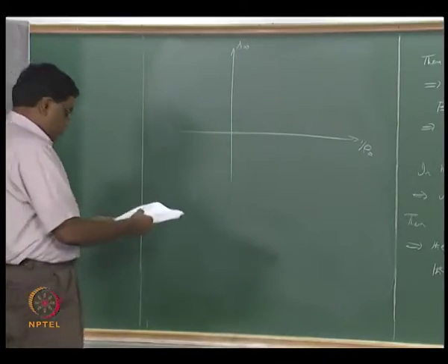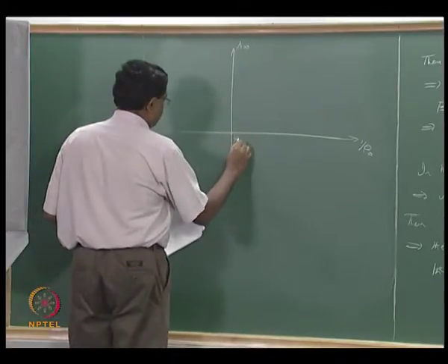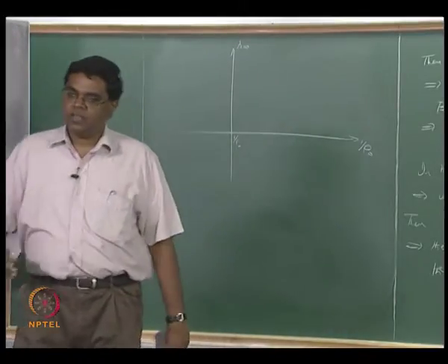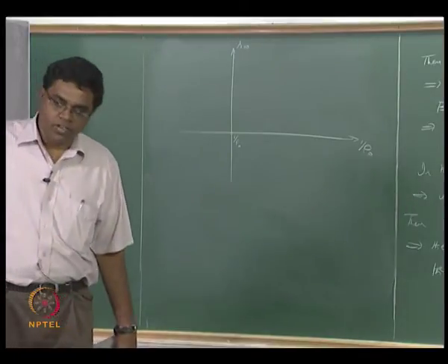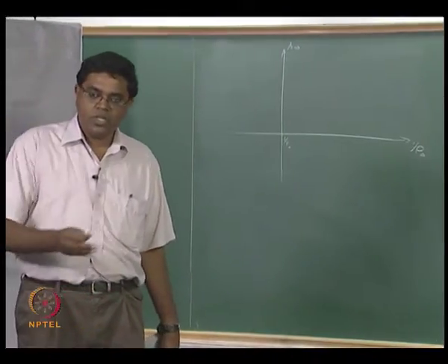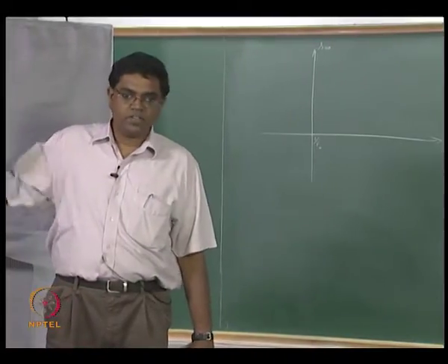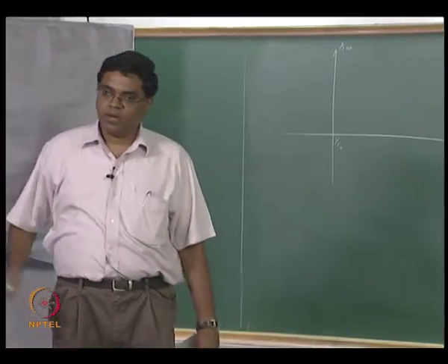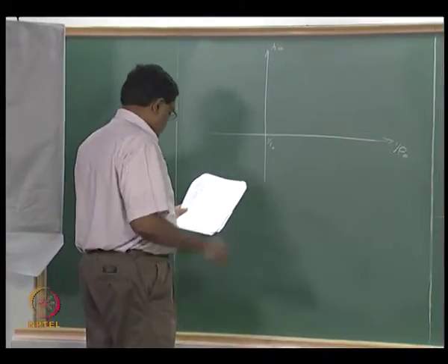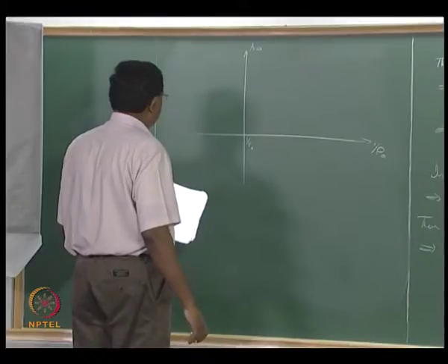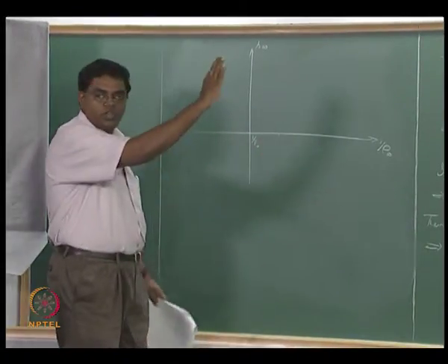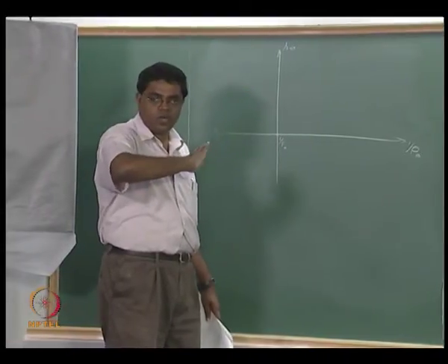The origin of the Hugoniot of course is 1 over rho naught, right, and then the 1 over rho infinity varies on either side. 1 over rho infinity increases in the deflagration, the lower branch, and 1 over rho infinity decreases in the upper branch for the detonation. But keep in mind that there is a region here which belongs to the first quadrant in the Hugoniot which is not covered, right.